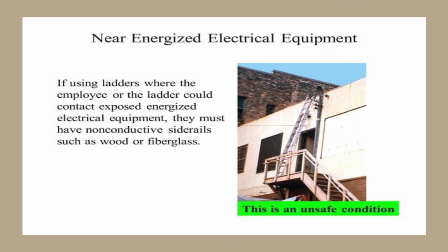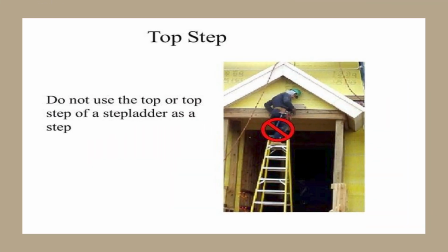Near energized electrical equipment. If you are using a ladder where the employee or the ladder could contact exposed energized electrical equipment, they must have non-conductive side rails such as wood or fiberglass. Top step. Do not use the top step or the top of a stepladder as a step.